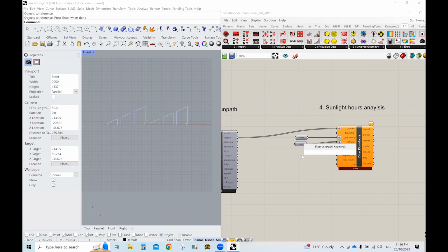So having done this before, I know that the computer will handle our 1 by 1 meter grid. So we can do our grid size as 1. But if you are unsure, I would start at either 10 or 5. And worst case scenario, you can do 10, run it again at 5, run it again at 2, run it again at 1. It's a lot easier than the other way around.